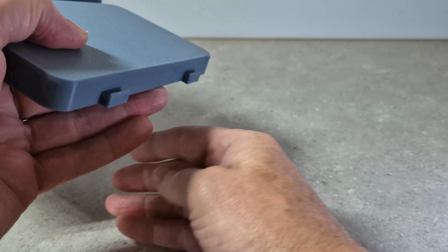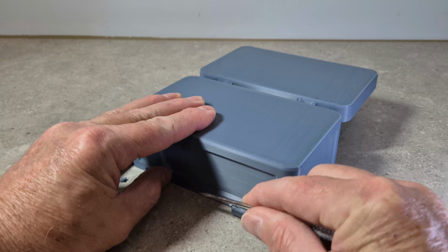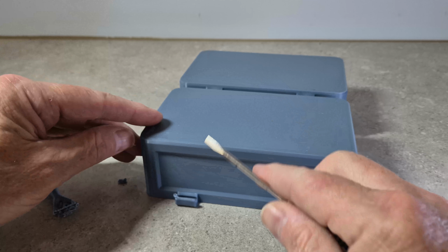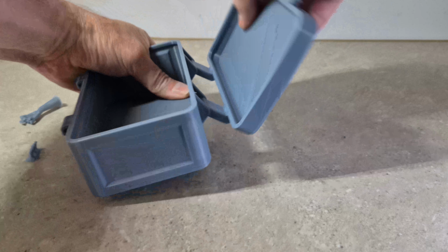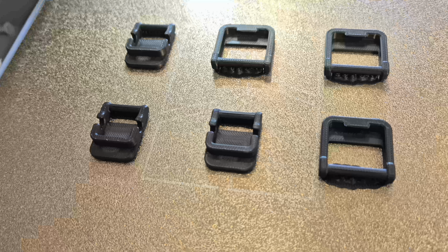Remove the tree supports, they should come off cleanly. If you need to, use a tool to remove any small portions of leftover supports. When breaking the lid free for the first time, ensure the part has fully cooled and rotate the lid while supporting the hinge. Now for the latches.